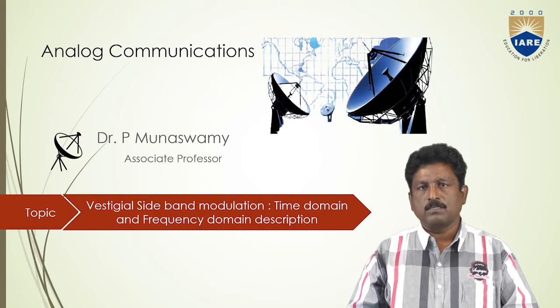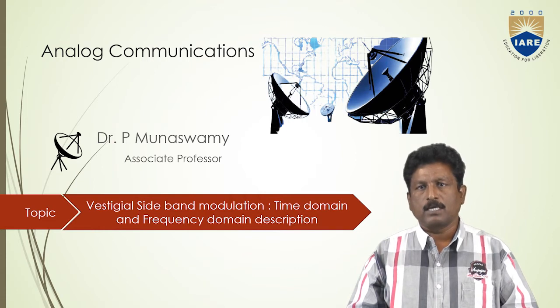Because of this, what are the electrical components used for reconstruction or regeneration of the carrier signal or modulating signal? We are using electrical components like resistors, inductors, capacitors, which decide the frequency of the carrier. With these components, we are unable to get the exact frequency because there is a tolerance value of these components.